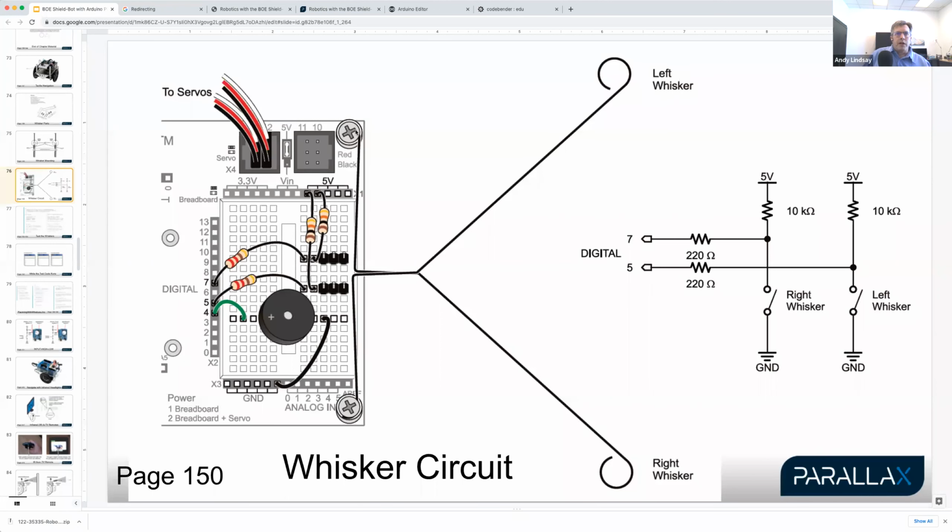And so because the whisker wire is connected to it, when I push on this whisker, this little part of that whisker is going to bump up against this 3-pin header. And what that will do, this 10K resistor here, I'm getting a little bit ahead of myself, but this lightly applies 5 volts to this row right here. And so the Arduino senses that 5 volts on P7. Now, when you push on the right whisker, this left, it bumps into this left 3-pin header.